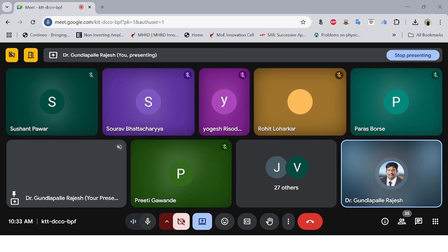But the most reliable one is multi-master mode, that is CAN, and the distance it covers is longer. The distance covered by I2C is very short, USB is medium, SPI is also short, UART is medium, whereas CAN is the one which can extend for longer.